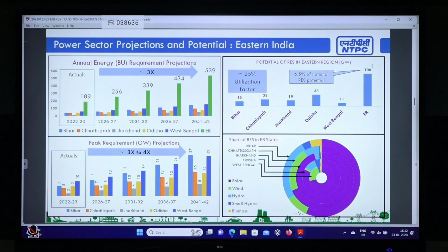That is not renewable. If I say there is no coal, no gas, nothing, then nuclear is the only option. So 50,000 billion units, that is terawatt hours, from nuclear means I need about 5,000 gigawatt of installed capacity. That means about 150 gigawatt every year I have to add over those 30 years. Nobody in the world has done so.